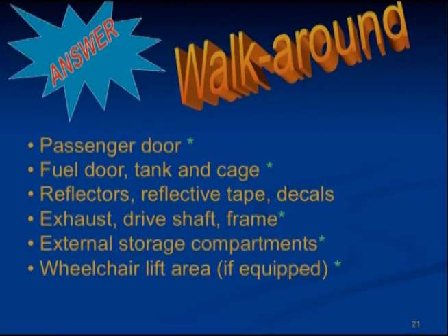Check vehicle inspection items and security awareness sweep to include the front passenger door area, the fuel door area, tank, and cage. Make sure it's secure, no leaks or anything unusual. Check the reflectors, reflective tape, and emergency exit decals are intact and not damaged.